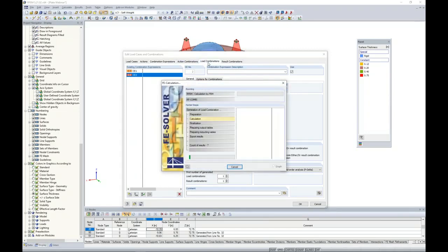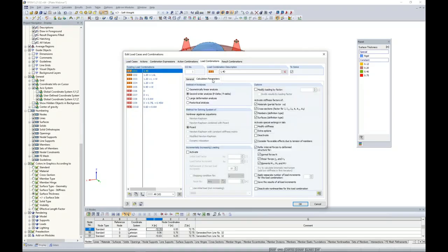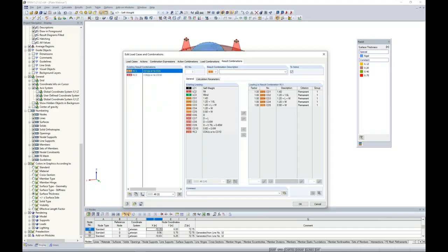The load combinations tab is going to list out all of the load combinations individually. So I'm going to see here my LRFD load combinations in orange, my ASD in red, based only on those load cases that I've defined. Keep in mind that with load combinations, the default method of analysis is second order. So we will consider both big P delta and little p delta. This is in contrast to load cases, which is run according to a geometrically linear analysis. This has to be done in order to combine it into load combinations and run according to a second order analysis. Now, finally, we have the result combinations tab.